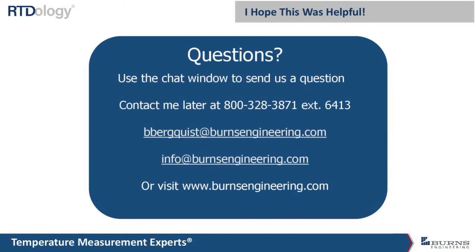Let's see. We have one that might have been answered already, but what is the minimum depth of an RTD probe to have no effect? Oh, yeah. And again, if it's a typical thermal well installation, 4.5 inches seems to work very well in water-like fluids. And again, to reiterate, in gases you typically need more than what you need with liquids.